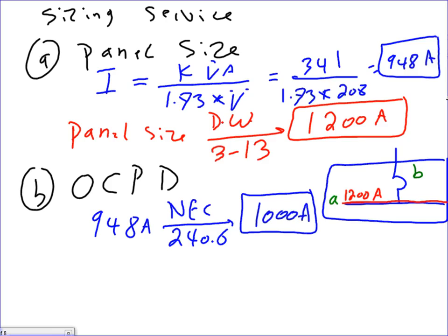So everybody knows where the 1,000 amp is now. I can't emphasize this one enough, guys. There's a B here, and what is this? 1,000 amp. Now, Holly, you're absolutely right. From a code point of view, this is a 1,000 amp panel, because the code says the amp of the panel goes by the amp of the overcurrent protection device. This panel could be a 400 amp panel, cover-wise. If I put a 200 amp ahead of it, it becomes a 200 amp panel.